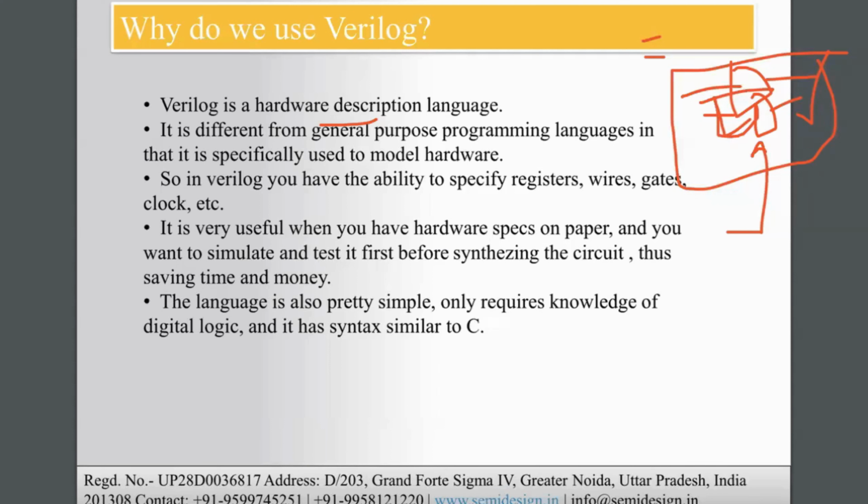Yes, ma'am. First, any program, whether you are writing the design or the test bench, will be checked for syntax errors. It doesn't check the functionality in compilation. It knows only about syntax errors. Once syntax errors are cleared, compilation is successful, and then it goes for functionality. If anything is wrong in terms of connections, or if any block is mismatched, it will generate the wrong output.